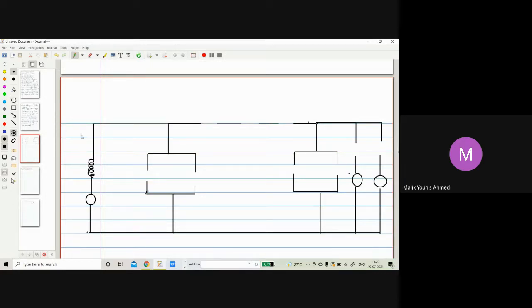Okay. So reactance of the generator number one, how much is this value? So j0.397, you can check them, per unit. So this is EG1, generator 1. Resistance of load A, reactance of load A. So resistance of load A is 0.75 per unit. Reactance is j1.549.